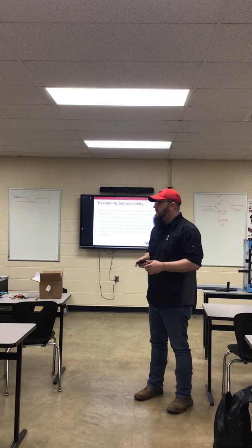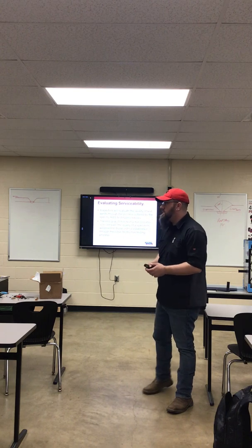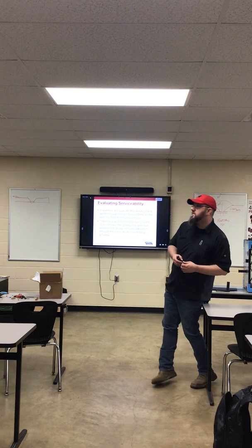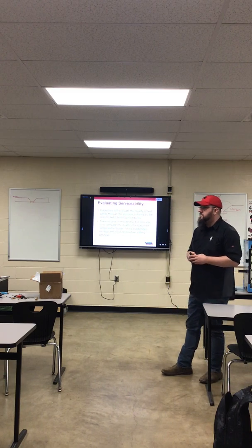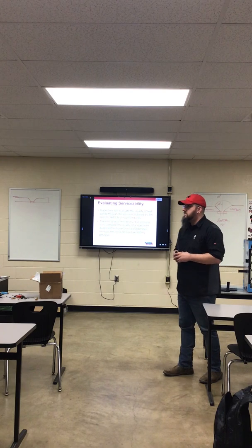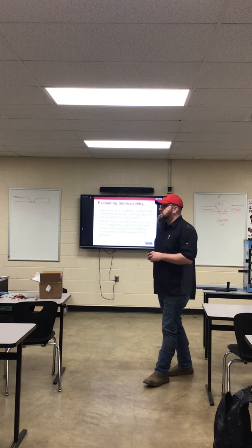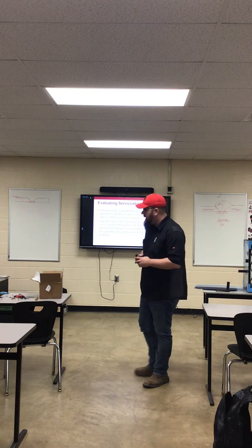Okay, our AWS D1.1 that we work with, what do we do? Cut up and down in strips, depending on the thickness of the base metal, and then cut off the strips and bend them. Okay.